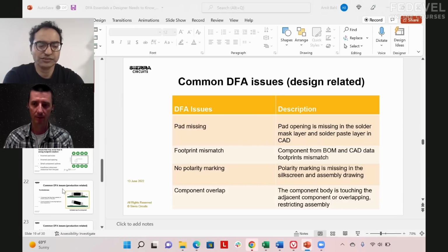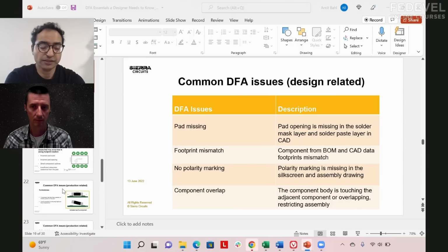So that's stencil design done by the fabricator. That's up to the vendor to decide what's the right way to put down the solder paste to get the right volume. So even if the designer doesn't do it, you will do it based on your experience. That's right. That's a critical step in assembly manufacturing, to get the stencil design correct. If your stencil design rules are not good, then you'll have lots of solder defects. That's the number one thing.